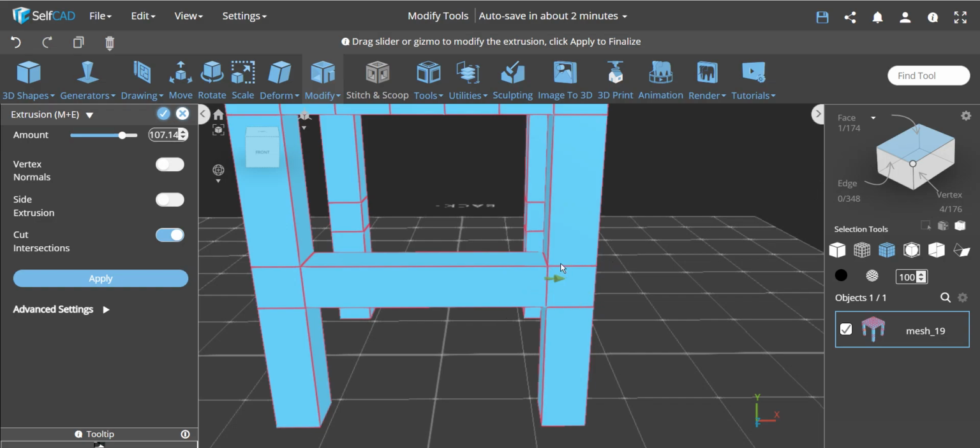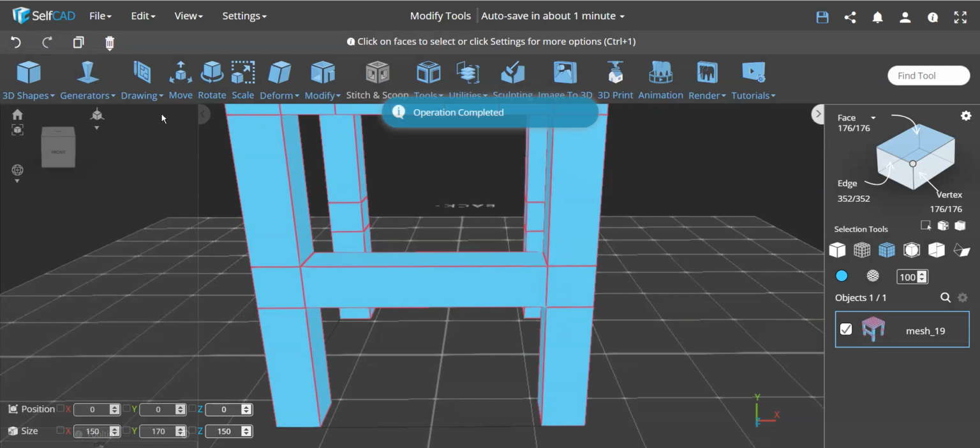As far as vertices, if you think about it, there's no vertex added actually, because all of these vertices that make up these side faces are already here from these faces. So I expect no vertices will be added. I have a total of 176, and I expect I'll end up having 176 vertices and 176 faces, the same amount. So let's see once I confirm that, and that's exactly what happened. There hasn't been added any vertex because these vertices are reused, and only 2 faces have been added.